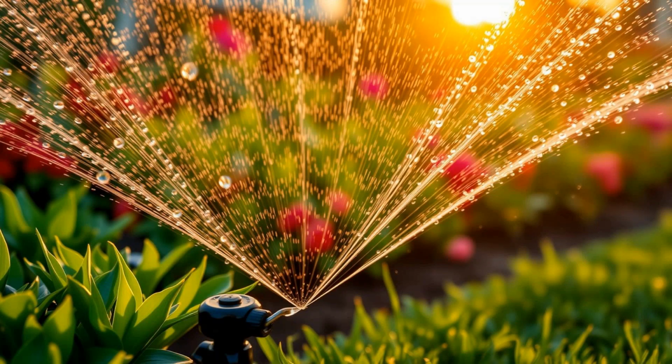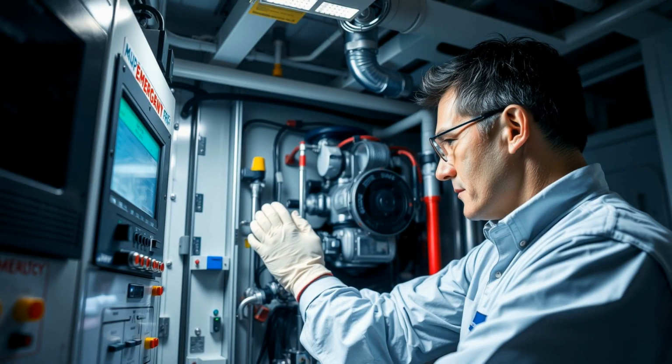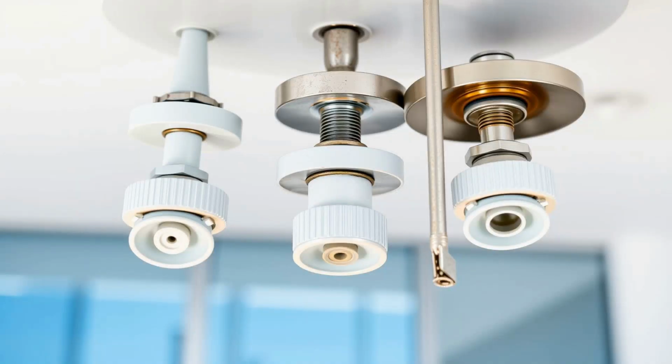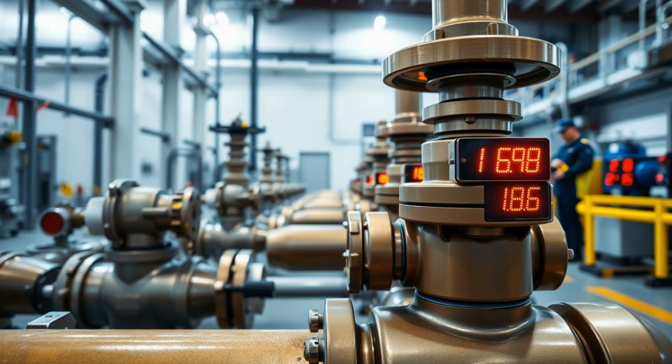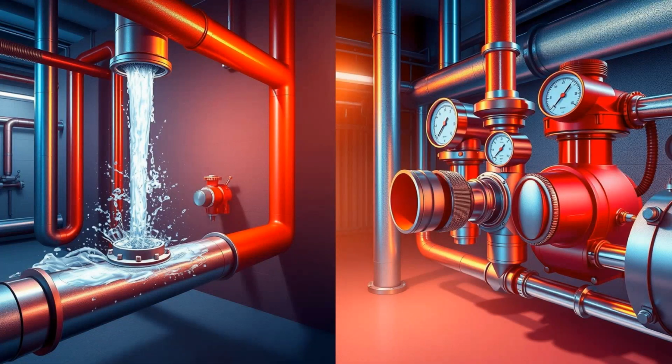Maintenance is another crucial factor in sprinkler effectiveness. Regular inspection ensures the system will function during a real emergency. Sprinkler heads should be free from paint, dust, or corrosion, and never blocked by furniture, decor, or false ceilings. Control valves must be locked in the open position, and water flow alarms tested monthly. Wet systems require annual flow tests, while dry systems need trip testing.